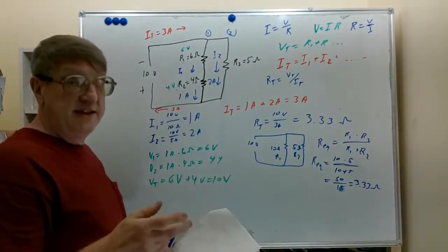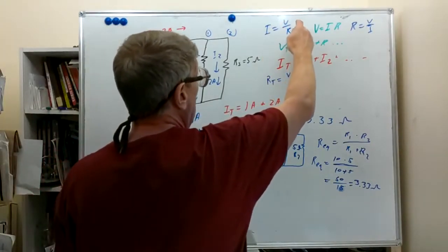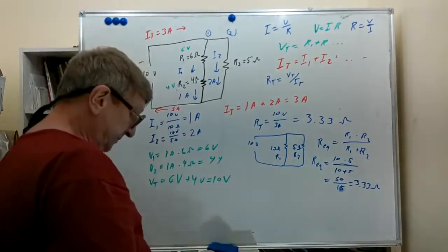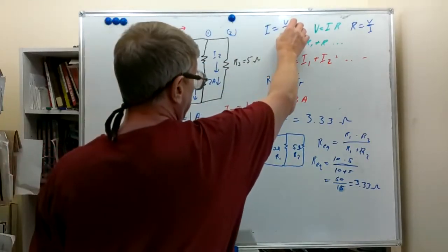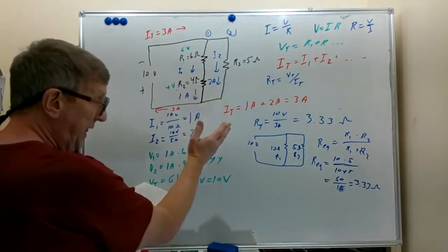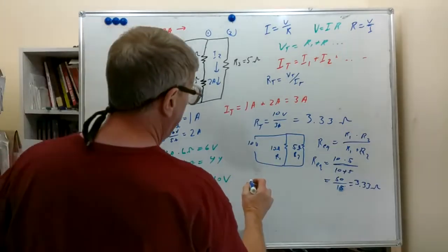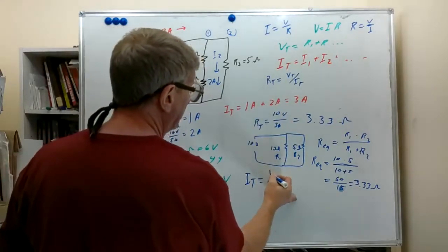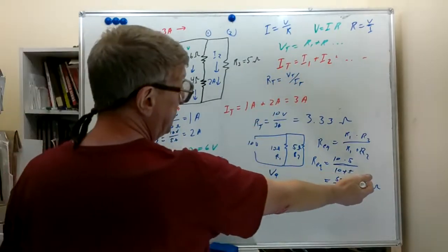And if you're trying to find your total resistance using this formula, the entire resistance, the entire network, has to be in this particular R when you use that to find out the total current of the supply. And of course, let's just do that real quick. We'll say IT, and we'll use this voltage of the supply. I'm just going to say voltage applied equals RT, which we calculated to be 3.333.